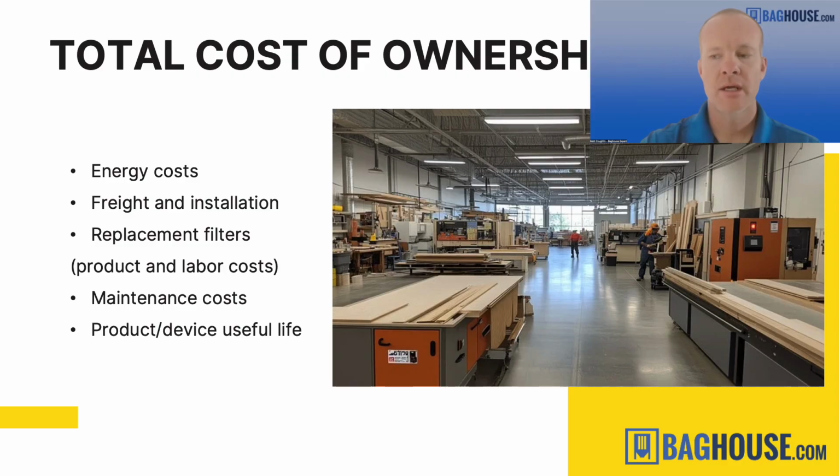Replacement filters. Everybody wants to know how often should I change the filters? So the correct answer to that question, unfortunately, is it depends on how you're loading the filters, how often you're using them, etc. So a small shop that's operating on one shift might change their filters every couple of years. A high volume production shop with a lot of dust that's really working their filters hard might have to change those filters every 6 months. It just depends how they're operating.